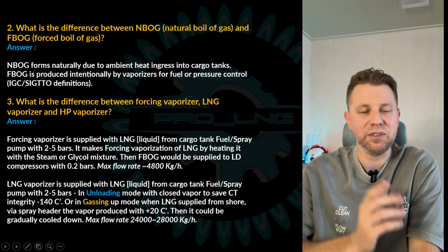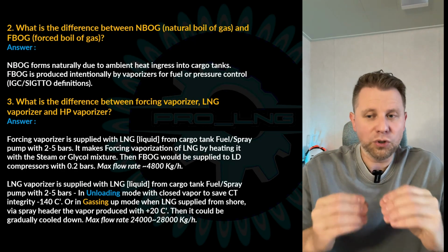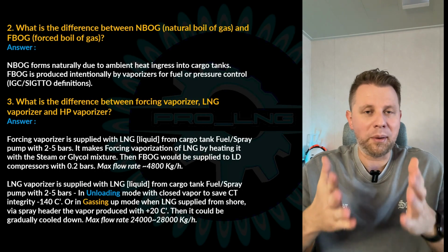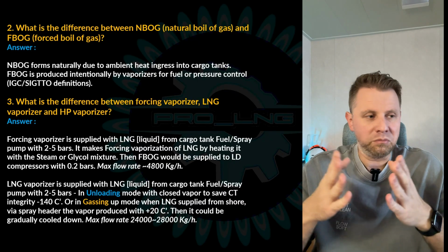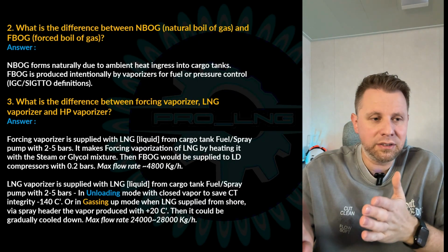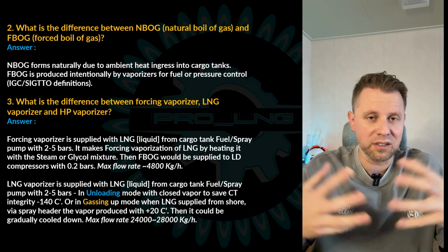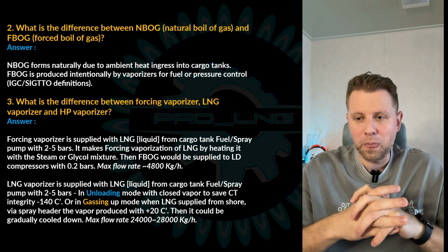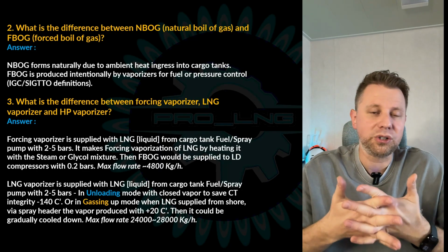Next one. What is the difference between natural boil-off gas and forced boil-off gas? Well, natural boil-off forms naturally due to ambient heat ingress into the cargo tanks. It's like swell, heat, also rough sea. All of these impact and affect natural boil-off. Forced boil-off is produced intentionally by vaporizers for fuel or pressure control.